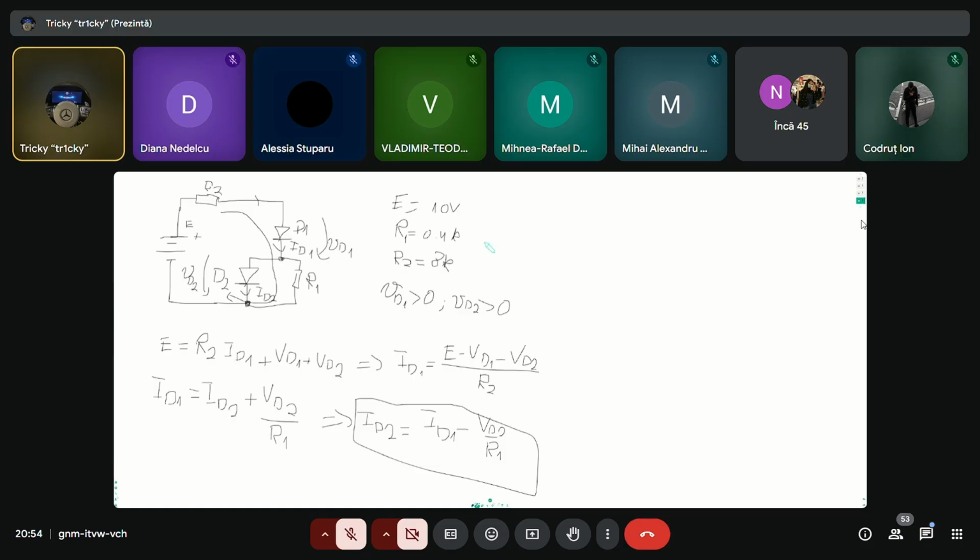All right. Let's go back. So we know here the currents ID1 and ID2, the ones that come through here, will be equal, and you can get those by getting ID2 as being equal to 10 volts divided by 8 kilo, and this will give us 1.25 if I'm not mistaken.